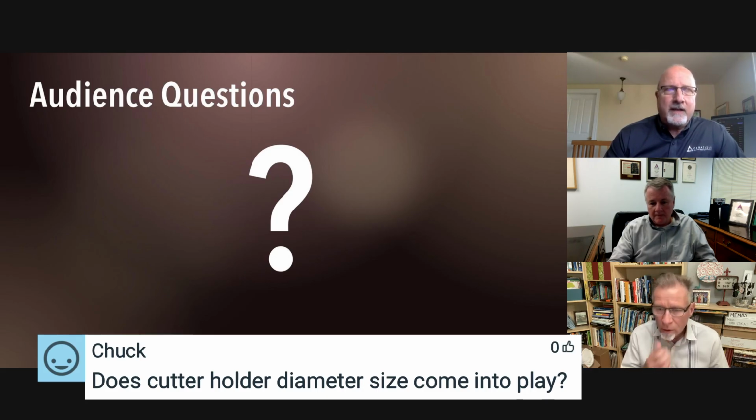So in that case, then you may have to deal with the diameter of the cutter itself, in terms of getting the RPMs where it needs to be to run the horsepower that you need to generate to perform that particular set of cuts, based on whatever the depth of cut is, feed rate, material type. I think that's answering this question. I'm not sure.